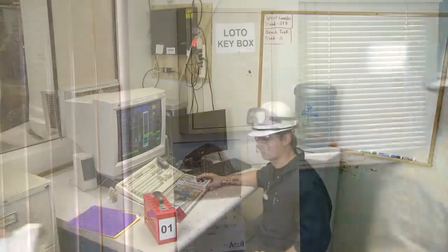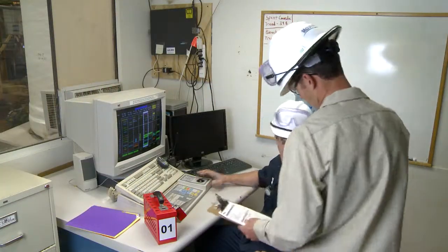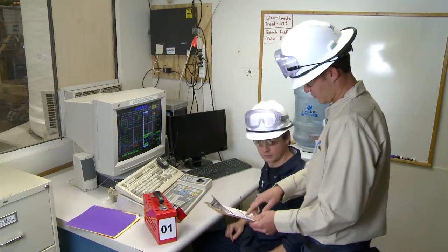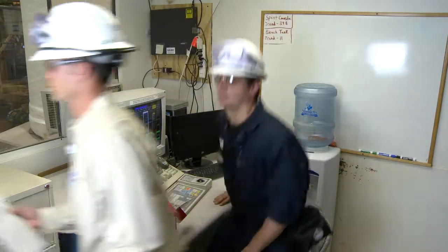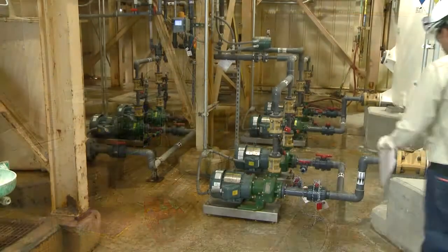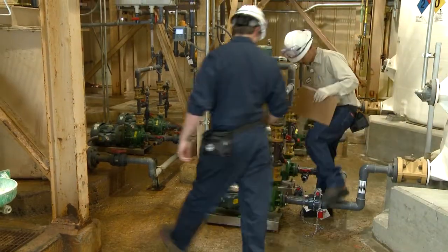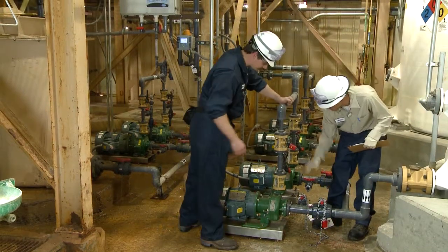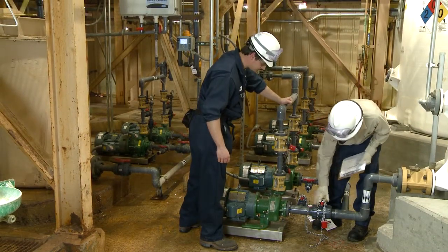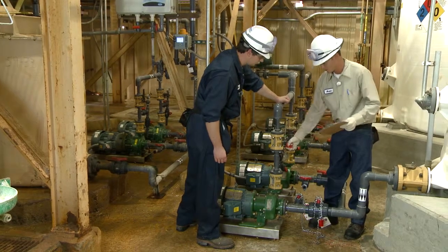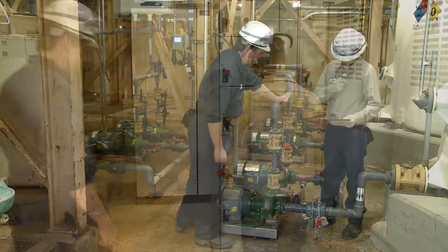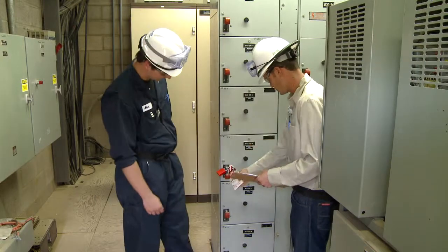At this stage in the process, the servicing representative who will work on the pump enters with a work order job card to start the pump replacement sequence. Before starting work, the process representative and servicing representative must inspect the system to be certain that it is properly isolated and locked out, starting with the valves. They must also verify that the breaker is locked out.